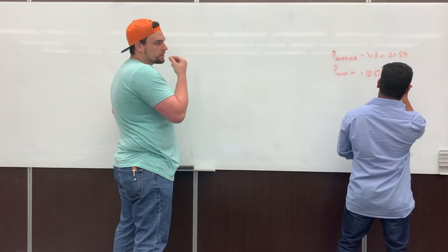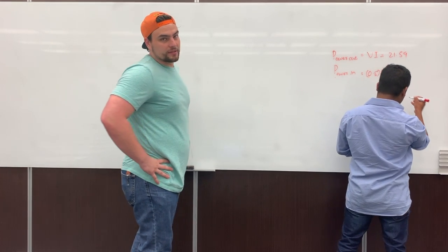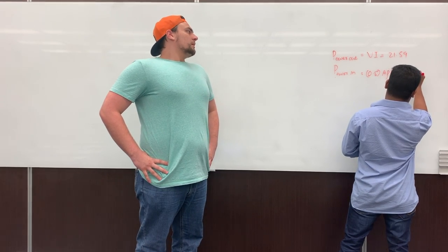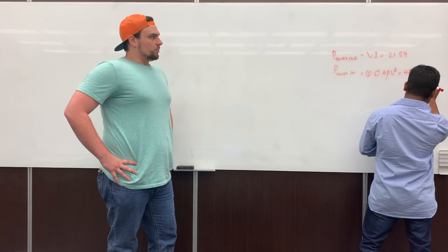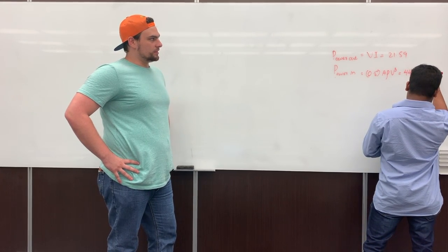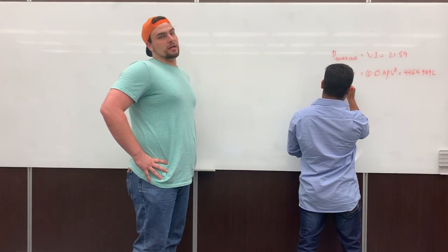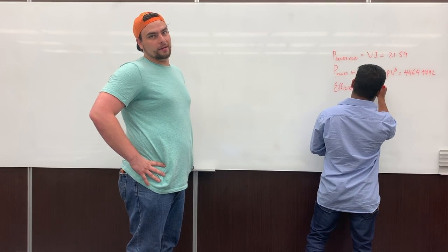He's writing it right here. It's going to be 1/2 of the area times rho. In this case, rho is density. That's the density of the air, I might add. He's also going to use the velocity, and he's going to cube it. Once we get these numbers, he's going to plug them into the efficiency equation, which, as in most of your sciences, is power out divided by power in.